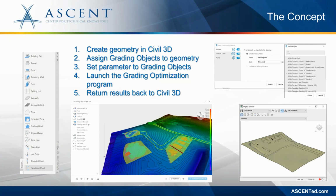And then once the optimization is complete, it goes through all its iterations, you can return the results back to Civil 3D. And you have the choice of either merging it with an existing surface, merging the feature lines into an existing site, or updating an existing point group, or you have the choice of creating new surfaces, sites, or point groups for your results. And then you finally have a Civil 3D surface that you can then refine with the various Civil 3D tools for grading.